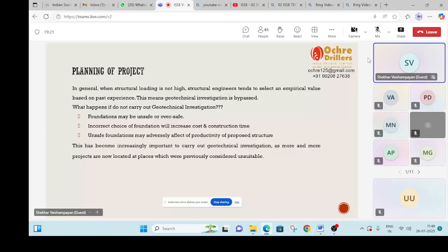Then one more thing I want to tell you. Say the site location is not suitable for you. It doesn't have a good view. It doesn't have a good drainage. It doesn't have, let us say, good founding strata. You dig a small pit and look. Then you find that okay, not workable. If this is not workable, I did not buy the plot. I just gave up the location.